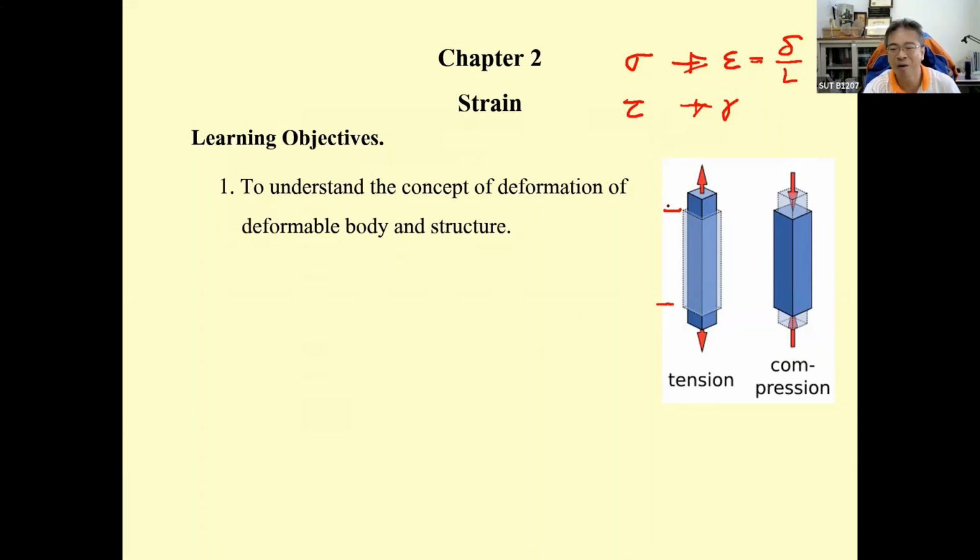The L is going to be the original length, but the shear is going to be another thing. Like I showed you guys with the sponge, when you move the sponge, you may see the angle here used to be a right angle. When you hook it like this, the angle will change. So this one will be defined as pi over 2 minus theta prime.